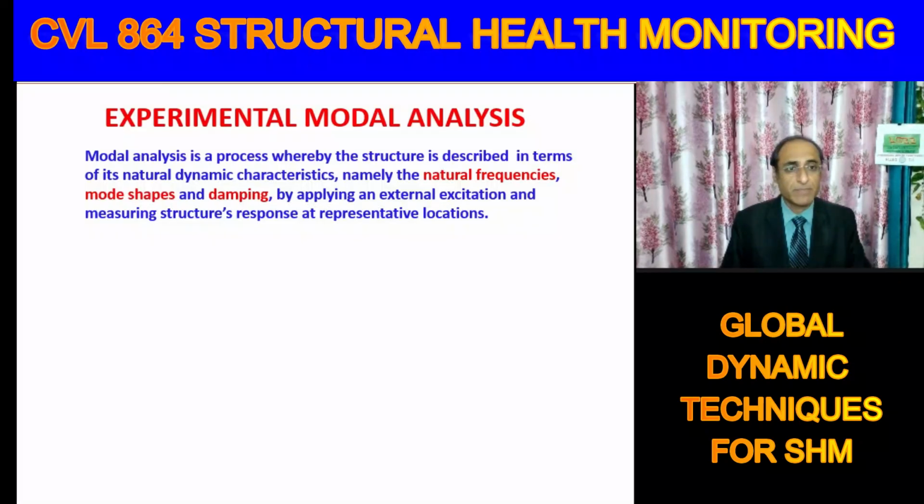So what is meant by modal analysis? It is MODAL, not MODEL. Modal analysis is basically a process where we identify the structure in terms of its dynamic characteristics. It's a very essential signature, forming representative dynamic characteristics: the natural frequencies, mode shapes and damping. And how do we do this? We apply an external excitation and we measure the response of the structure at some selected locations. So this is how we perform experimental modal analysis.